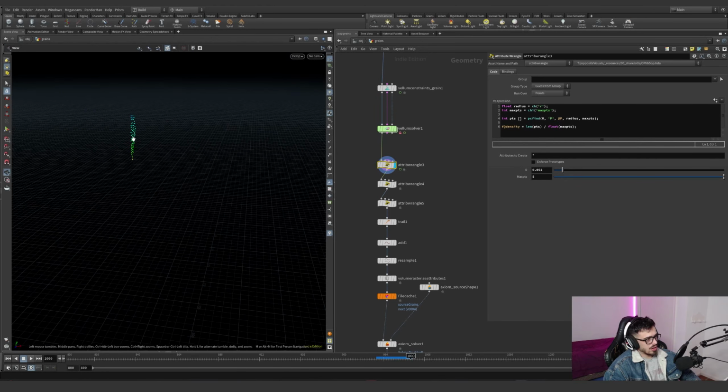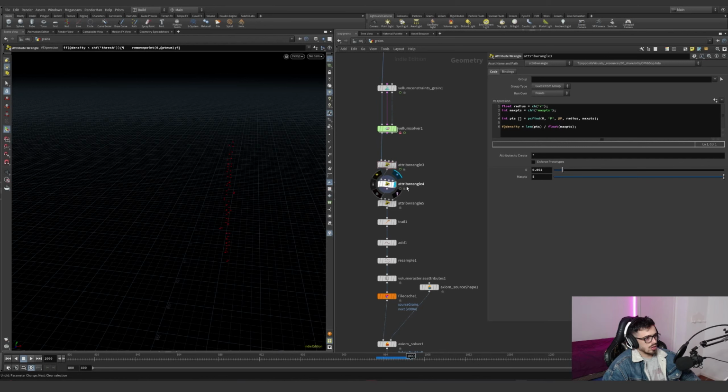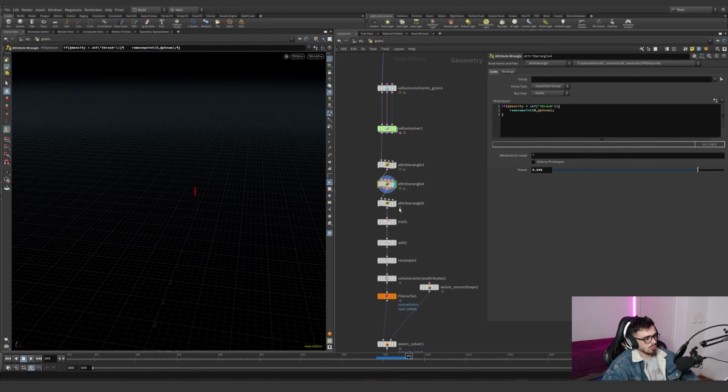Yes, I'm going to calculate, based on the PC find, the density of the points. This is a good trick, which is shown like this. As you can see, I'm going to find how many points are in this radius and how many points I want to look for. The more points I have, the less I'm going to have density. I mean, the opposite. If I have more points nearby, I'm going to have more density. In this case, I'm just using this to delete everything that's far from the main blob of points, because I want to have straight small lines.